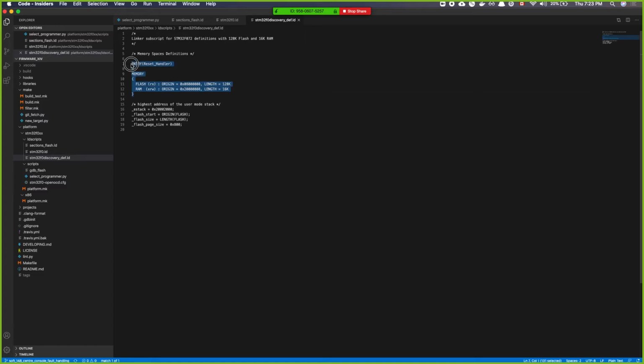But yeah, this is where you define your memory sections, because when you write code, your code must know where the memory exists. And this is what your linker does, because your code generates an object file, and your object file reads and writes from memory. Your code gets compiled down to machine code, but for the address values, you still don't know where the addresses start and end. So all of the addresses in your object file are merely offsets. Where those offsets should start from is where your linker comes in and makes that happen. So your linker is where you define your memory.